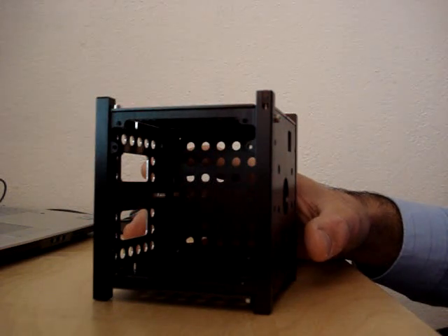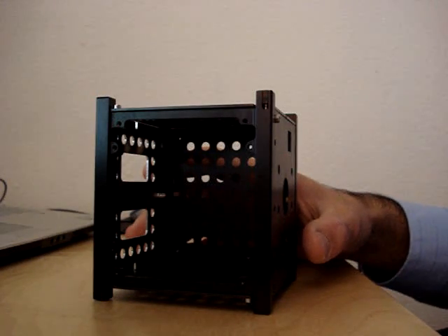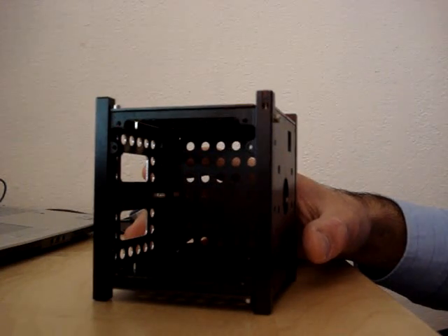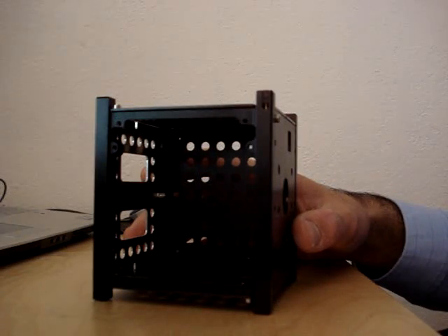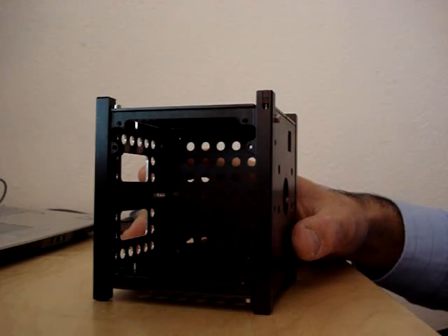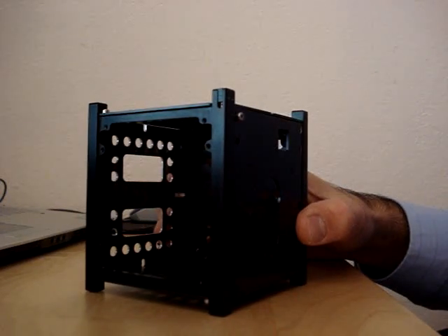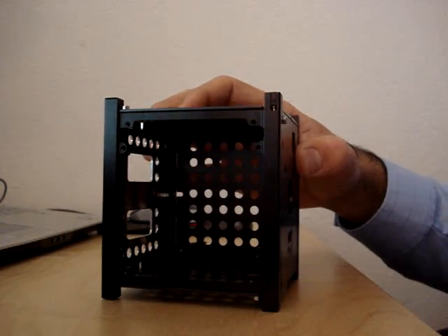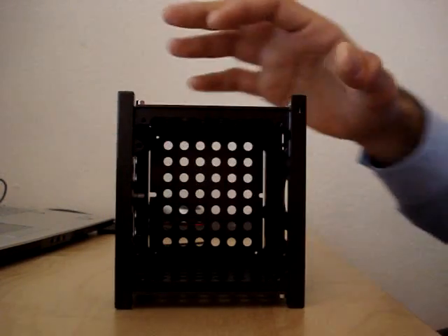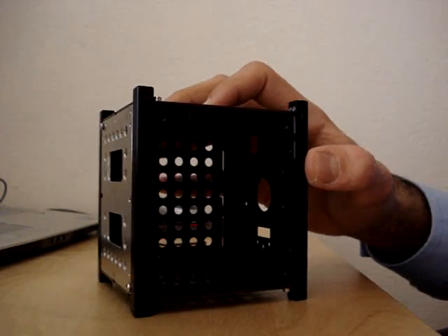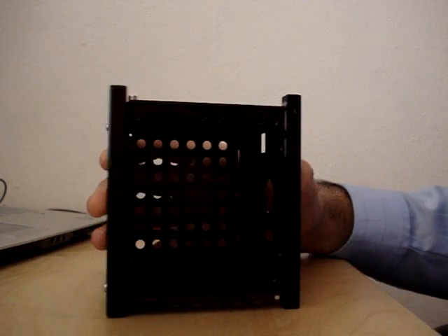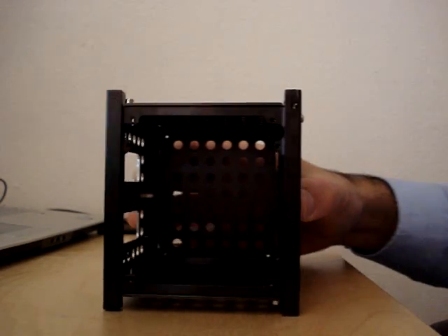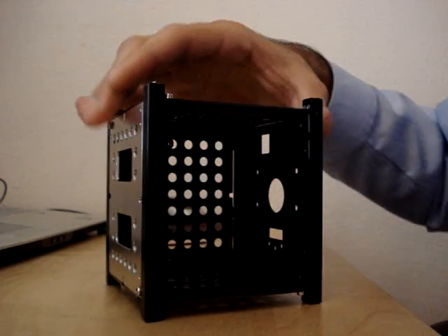I learned a lot from this person, this machinist, and a couple of the manufacturing engineers at the machine shop about the idea of design for manufacturing and design for assembly. It really opened my eyes to ask myself questions like, how can I reduce the time it takes a machinist to program the machine to make me this part? Or how can I design this so that there aren't any complicated setups required, so that all it takes is one simple setup on the CNC machine and you could start machining the part right away.